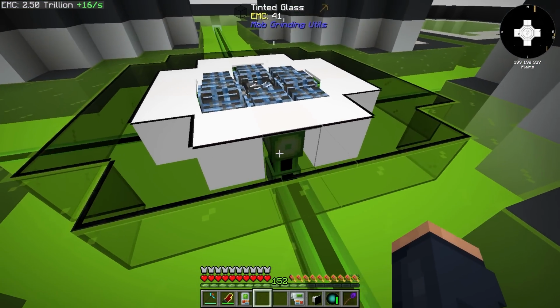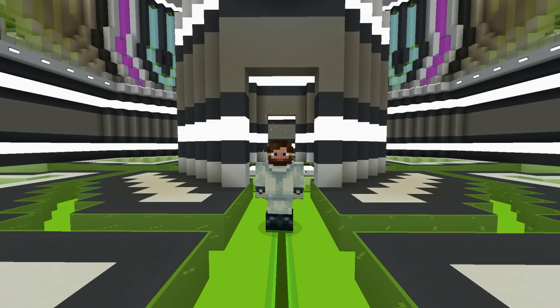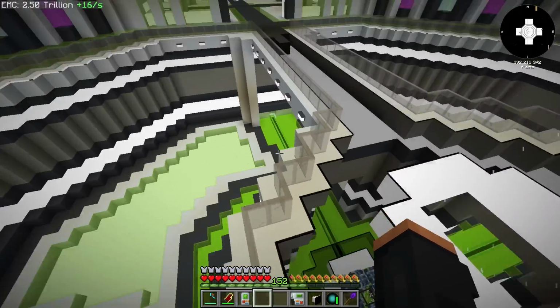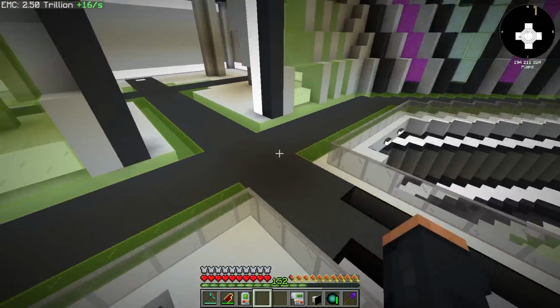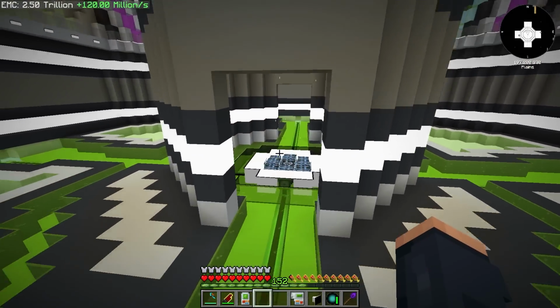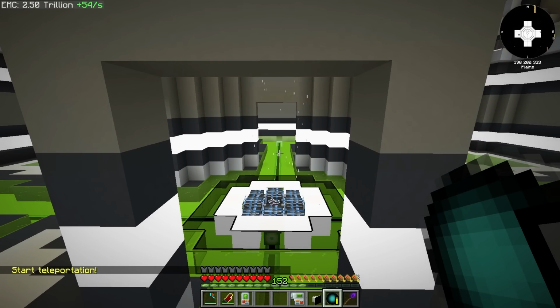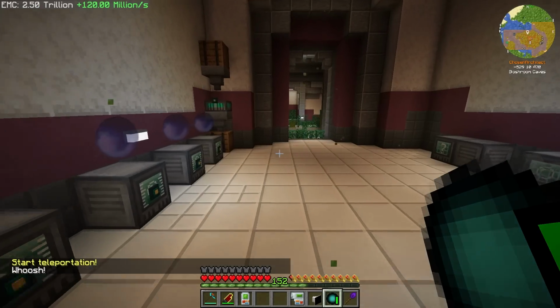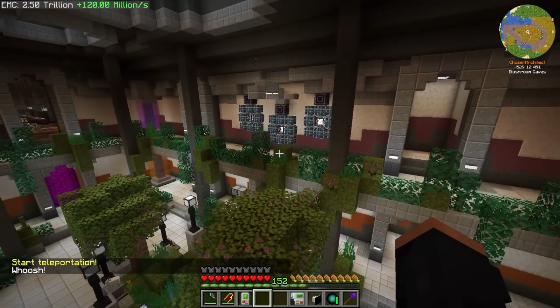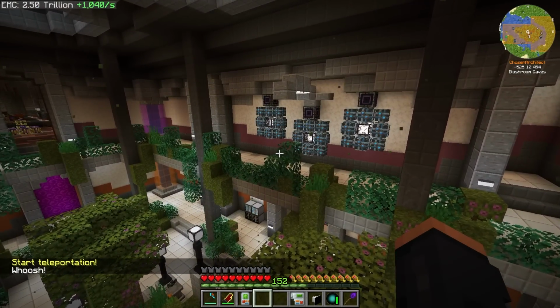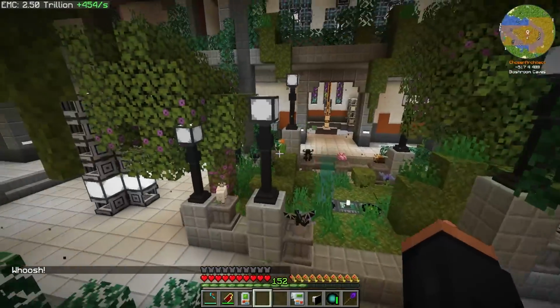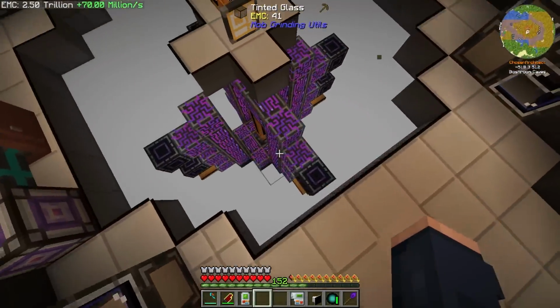But what I've done is I've just run some dense cables. Now I have some interesting logic around how I am going to handle my channels using that point-to-point system. And my logic essentially consists of carrying out these dense cables, which is going to carry our default 32 channels. So in reality, we're only sending 32 channels into these dimensions, but we'll have access to a ton more channels from our controller by utilizing that point-to-point system.